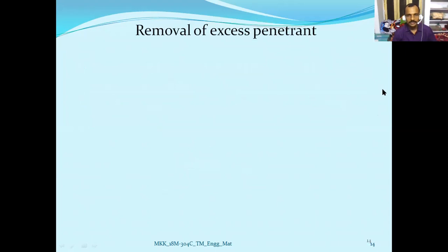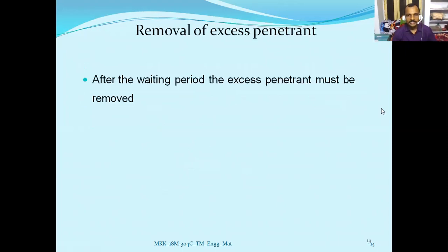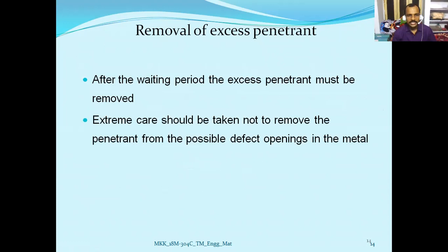Next, after the waiting period is completed, the excess penetrant must be removed. Extreme care must be taken to remove the penetrant. If the penetrant available in the crack or defect is not removed, then there is no chance of clear visibility of this particular flaw or defect.